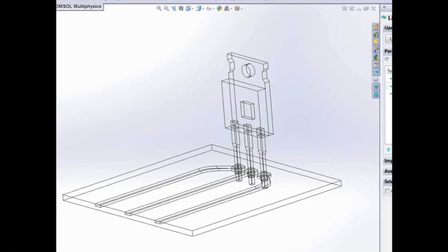So basically, it contains these two dimensions, and they are associated to a COMSOL parameter that was automatically created when I started this model. And it's important to have this because COMSOL is working in its own parameter space. So for the COMSOL solver to be able to drive a parameter to change its value, we need to have a parameter that is associated to a SolidWorks dimension.